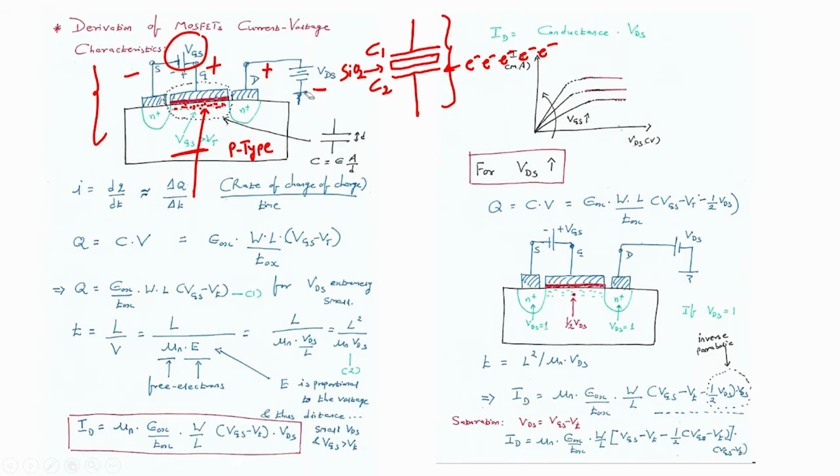So here we can see that a capacitor forms when you apply a positive gate voltage, due to which the electrons from the substrate get attracted towards the gate and form the channel. This channel forms one plate, the metal through which the contact is taken forms another plate, and there is an insulator between the two conducting plates.